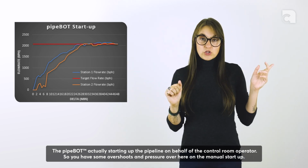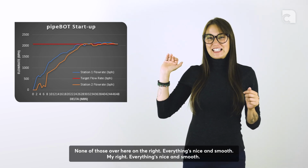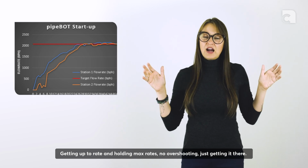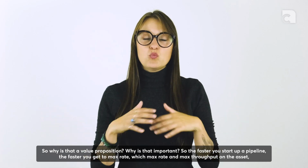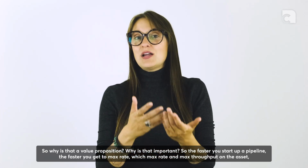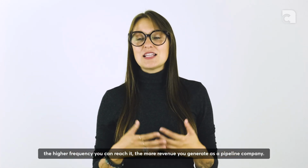You have some overshoots in pressure over here on the manual startup, none of those over here on the right. Everything's nice and smooth, getting up to rate and holding max rates, with no overshooting, just getting it there. So why is that a value proposition? Why is that important? The faster you start up a pipeline, the faster you get to max rate, and the higher the frequency you can reach max throughput on the asset, the more revenue you generate as a pipeline company.